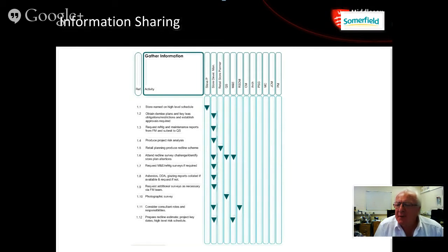Graham, yeah. We use IFC as the format for federating models across native software and using a 3D environment, but don't understand how the raw data is used by others outside the 3D environment. Not sure what you mean by the raw data, Graham, but when somebody tells me they're using IFCs, I always want to know to what extent. I mean, for example, did you use IFCs to detail the damp-proof membrane at the bottom edge of the building, or the roof coping at the top edge of the building? My guess is you probably didn't.